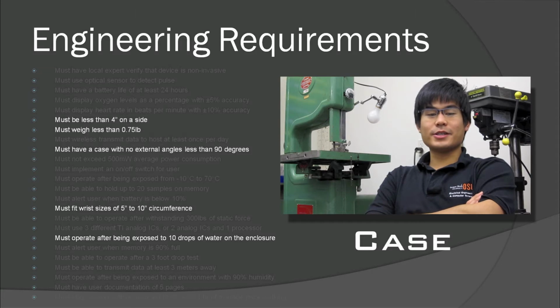These requirements were chosen to ensure the durability and convenience of the product. Ideally, customers will be doing everyday activities while using this product. Therefore, a comfortable while robust enclosure is required. The biggest challenge in this block will be the size constraint. Being able to fit the whole system comfortably on a customer will require the use of small but condensed components. With that in mind, all the components in the circuitry will be surface mount parts, and the battery, which is the biggest part in our system, will be 1.76 inches by 0.8 inches by 0.3 inches, way less than the limit of the 4-inch requirement.